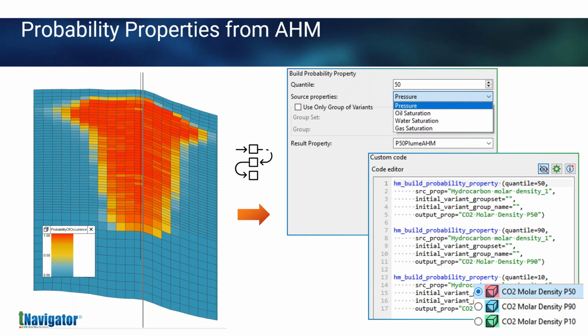So in this case, we wanted to do it for all 3 and not to repeat this. So basically made a copy of it, copy paste, and just change these variables here. So instead of 50, we put a 90 and change the name of the output property. It's quite easy to set up, even if you're not very tech savvy or into Python programming.